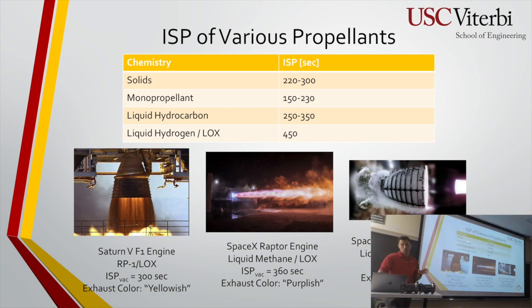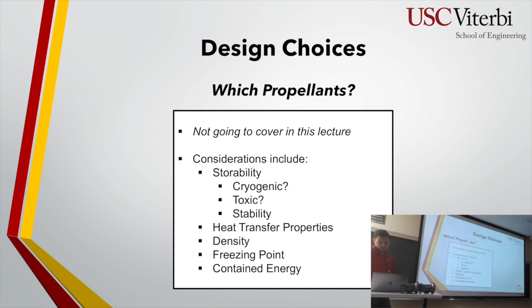And then there's also a whole other thing that, if you take the launch vehicle design class, it'll go into. If you ever notice, every single launch vehicle typically uses kerosene for the first stage, and then for the second stage you might use liquid hydrogen. It's because of the density. You need to bleed as much out in the beginning, so you want denser things for your first stage to overcome that initial gravity you have.